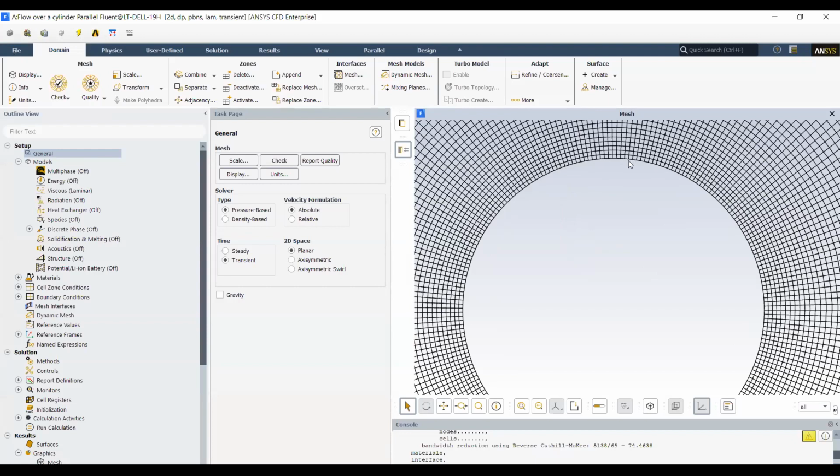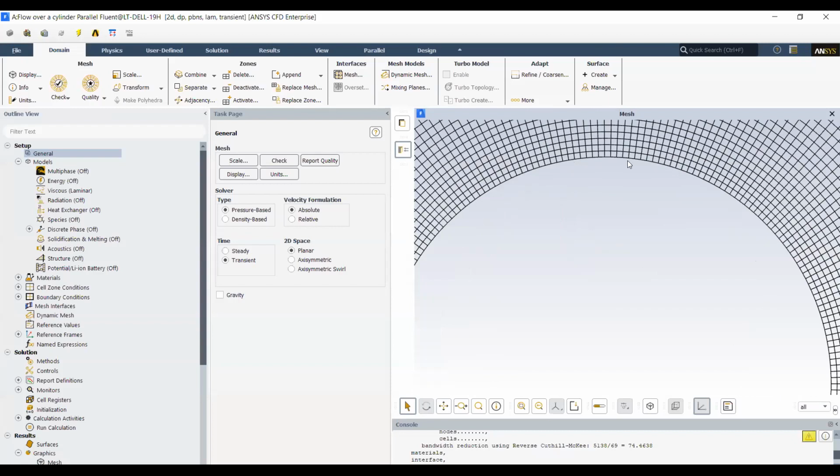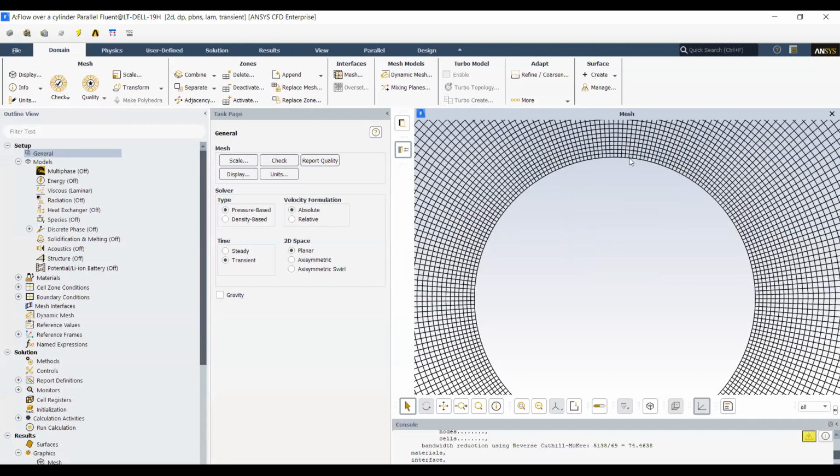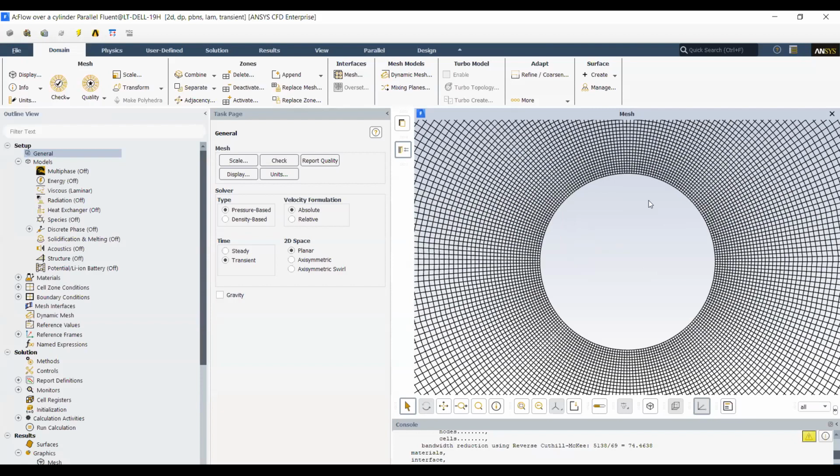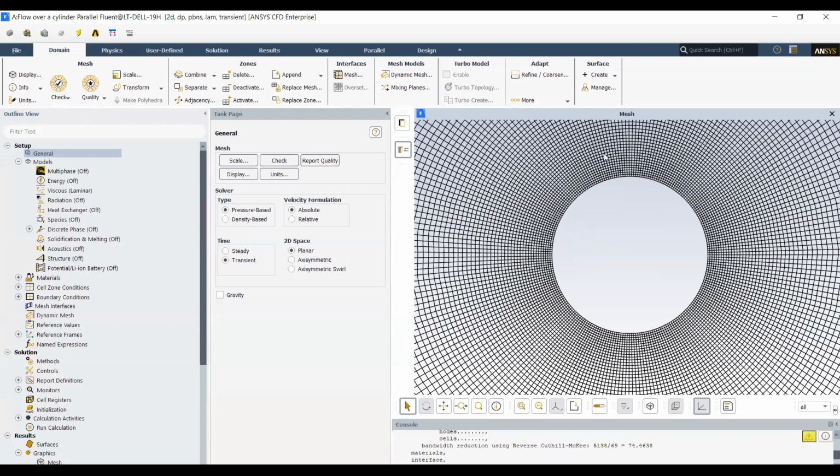Since the wall is stationary, the velocity of the fluid is also 0 at this particular point. Now this velocity of course changes as we move away from the wall. This change is more drastic near the wall for any particular flow application. So in order to capture those gradients, you will need to have a finer mesh near the wall region for any application that you simulate, right?